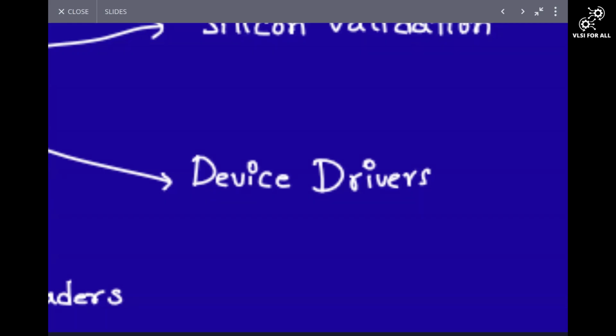In order to control that ADC, we need to write some registers. Let's say if you want to turn on an ADC, we need to write one to a register. In order to start the ADC conversion, we have to enable some bit. All these bits are stored in some registers related to that ADC. Now, to validate the ADC working, these post-silicon validation guys had to program these registers using code, or manually set those bits in those registers, right? So that's why you also need to have knowledge of programming registers when you're validating your design, right?